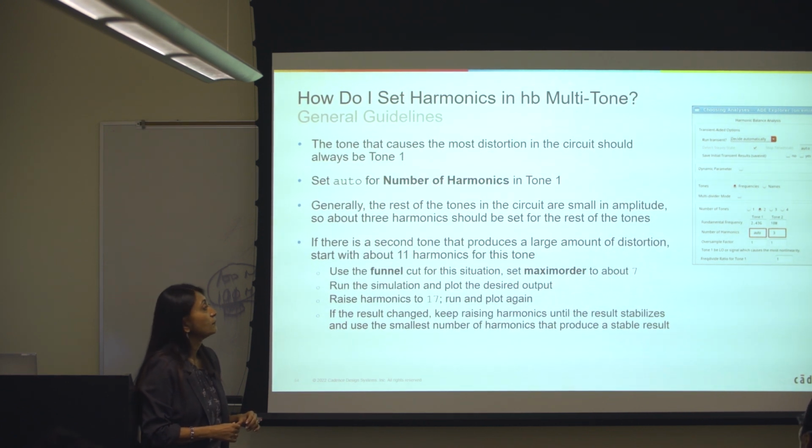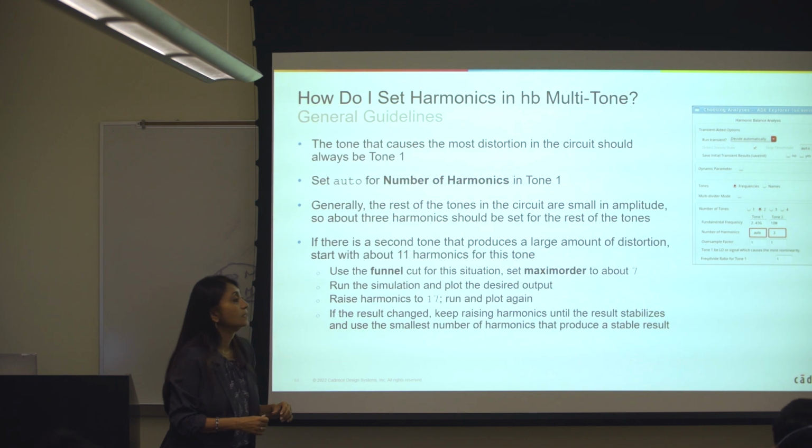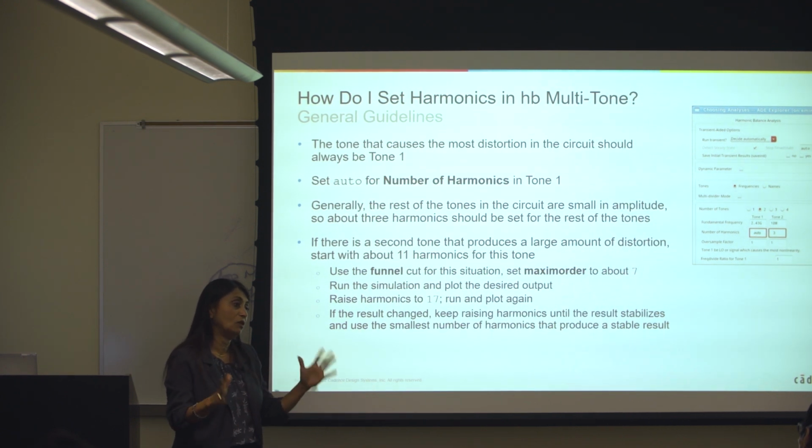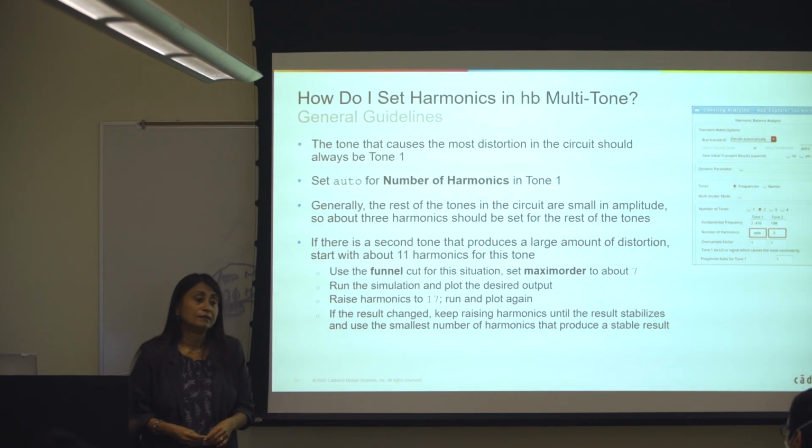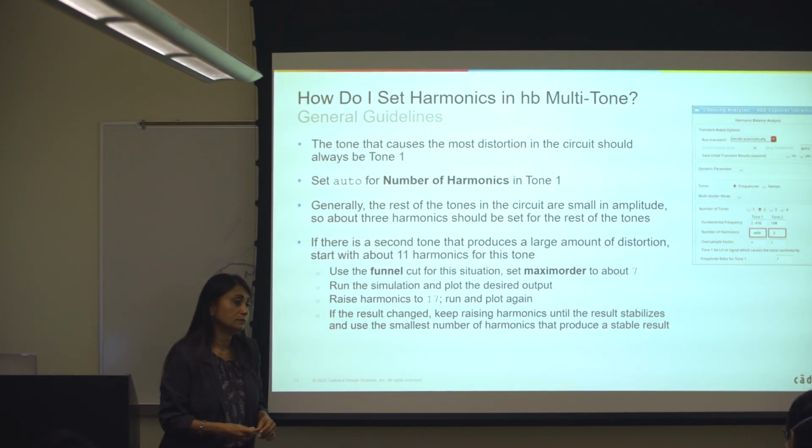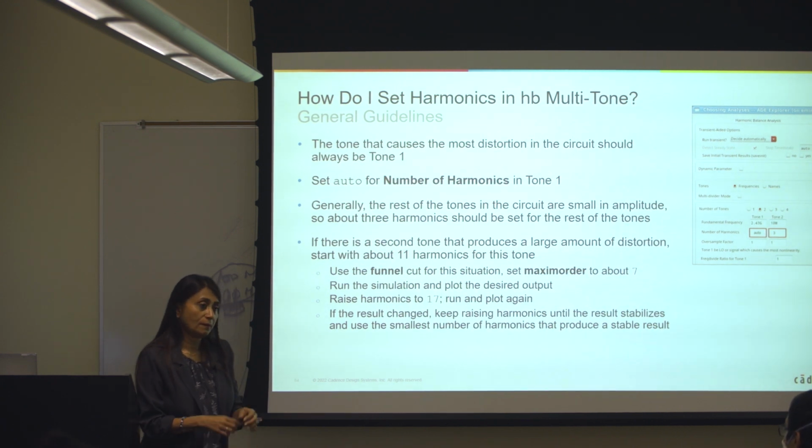I would use QPSS when HB is not a possibility and when PSS is not a possibility. I would not dive straight into QPSS unless there are so many tones, all nonlinear, and with so many harmonics per tone.